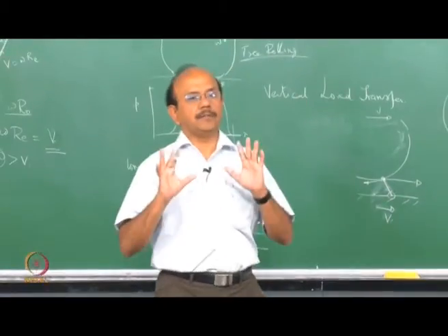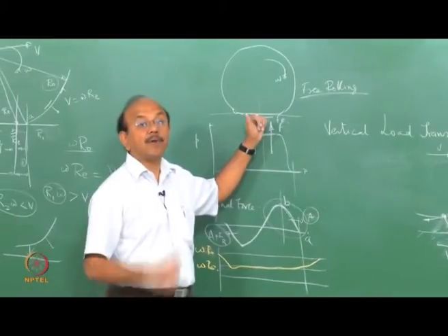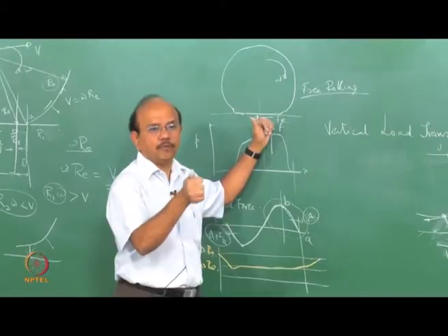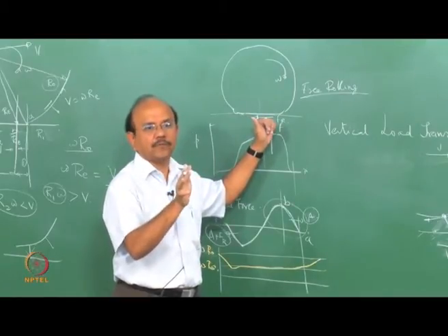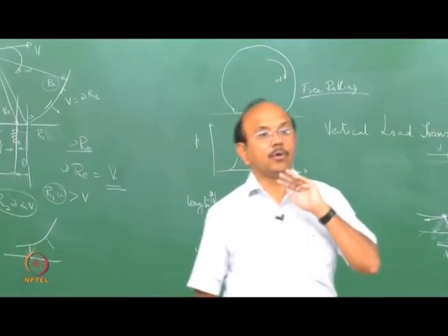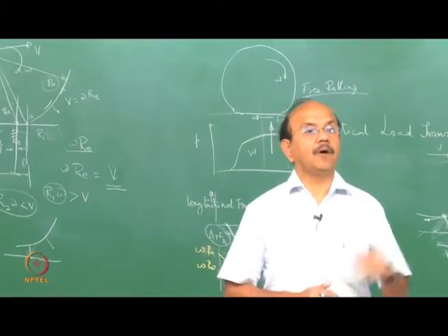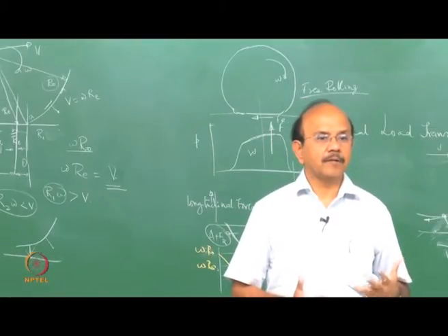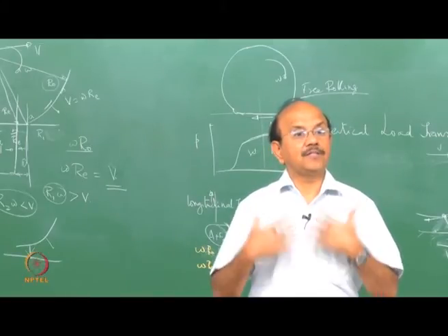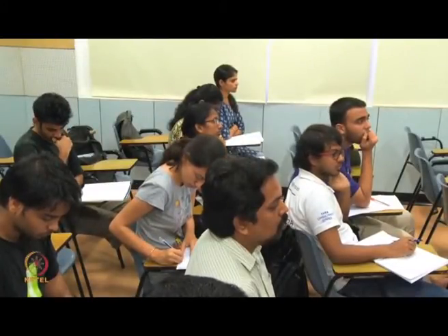Right now, understand that I am not applying a longitudinal force, either to brake or to accelerate. Under these conditions, the only force that acts is the rolling resistance force, and the rolling resistance force has to be compensated. Clear? Right.